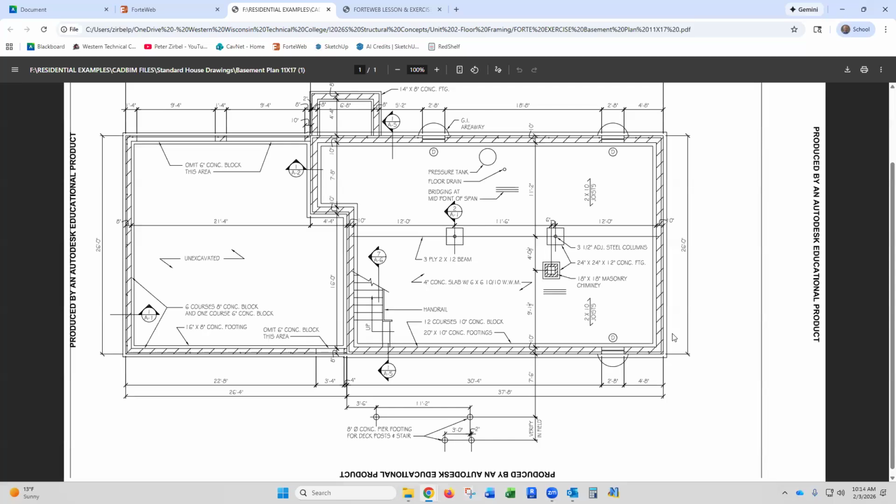Yeah, if we're sitting on the plate on the wall, is that a 2x6 or a 2x8? Depends on what size your foundation wall is. Yeah. 2x6. I picked a 2x8 in this case, so we're going to do a 2x8. Okay, so that's where we're going to go. We're going to go 26 feet out to out.